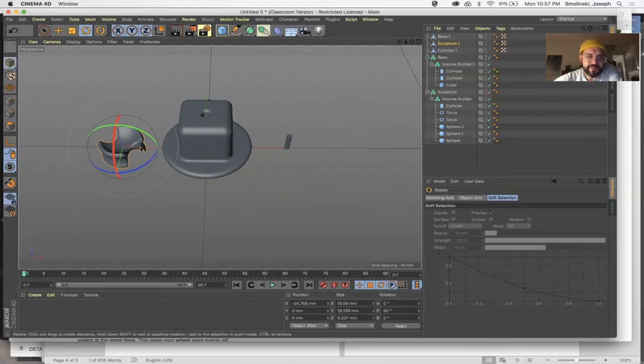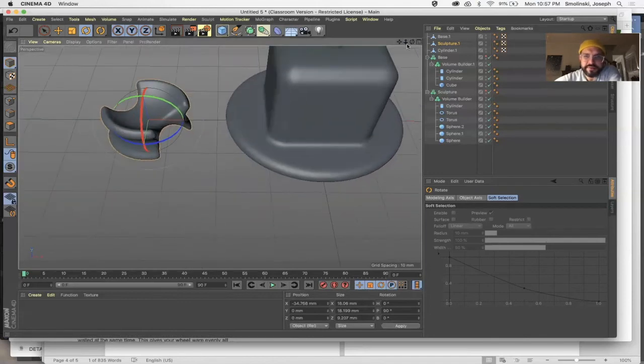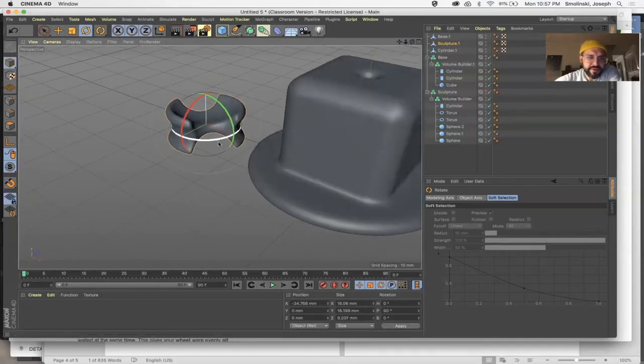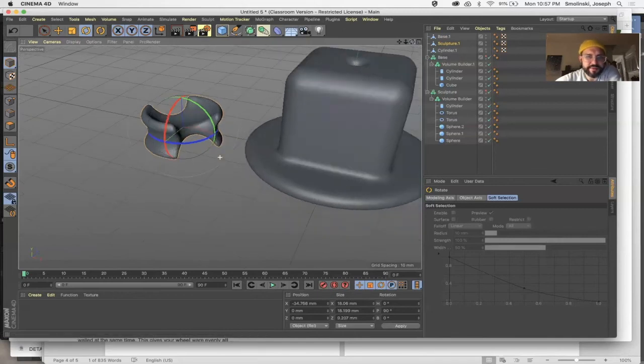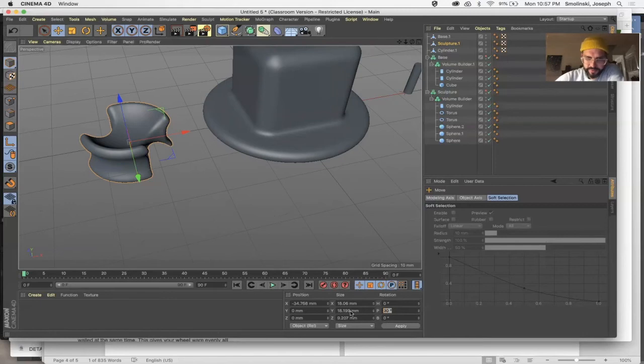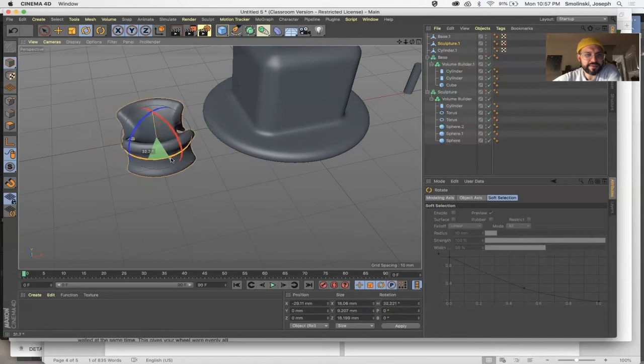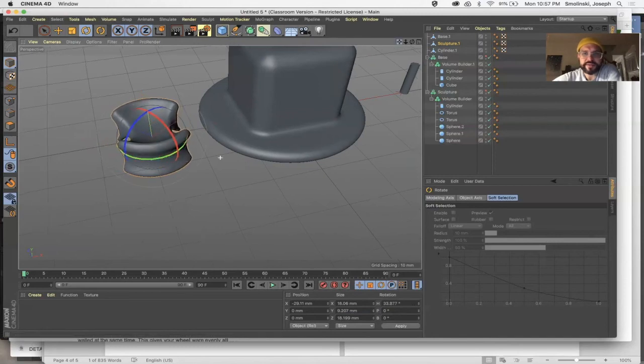Scaffolding or the bridging that it creates to kind of print underneath objects or in the voids. It may or may not need any underneath here, but I think in this orientation is probably the best to print. So I'm gonna take this, again, go back to my move, enable access, and I'm gonna go to the rotation and hit 0 just to get that Y axis pointing back up straight again. So that's pretty good. I'm just gonna bring this in a little bit closer. I might actually just rotate it a little bit. That looks pretty good.